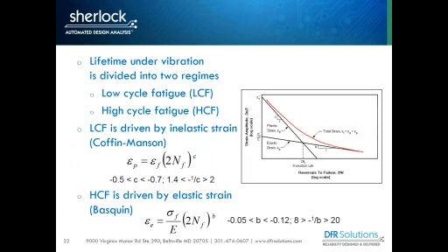So again, I'm going to stress this one more time. In low cycle fatigue, creep and plasticity happen very quickly. When we're talking about high cycle fatigue, it's really a stress law, elastic. You can see here, this is the S-N curve. We're talking about things down here for vibration. And you can see very small changes in stress or elastic strain can have large impacts on time to failure. I can change my stress a little bit, and it can have an order of magnitude influence on time to failure.